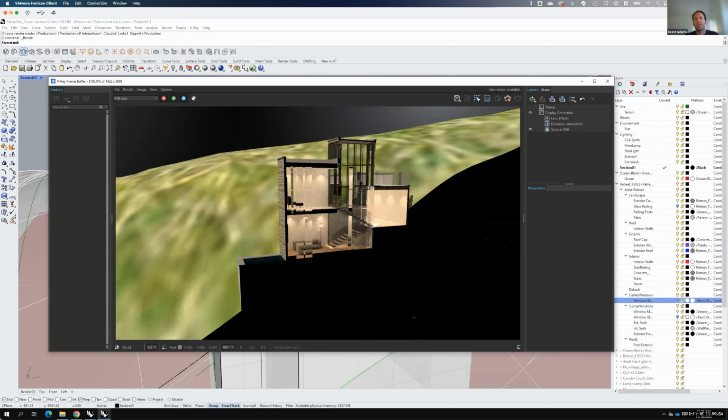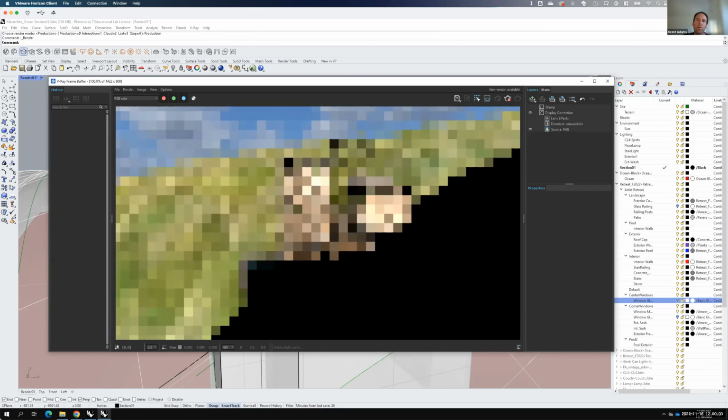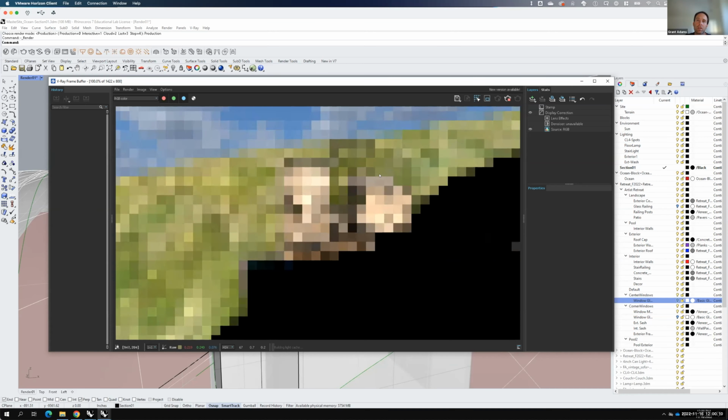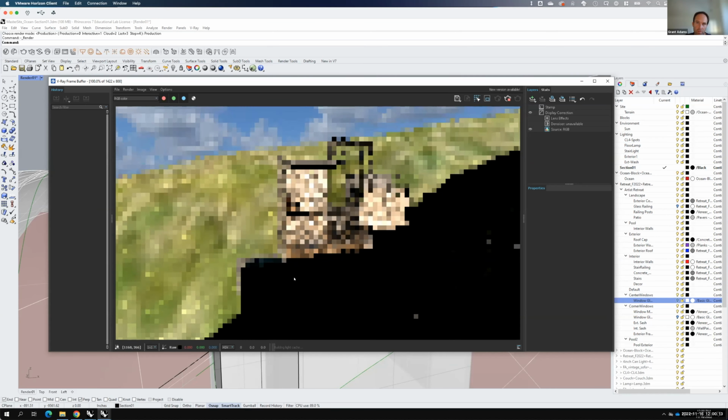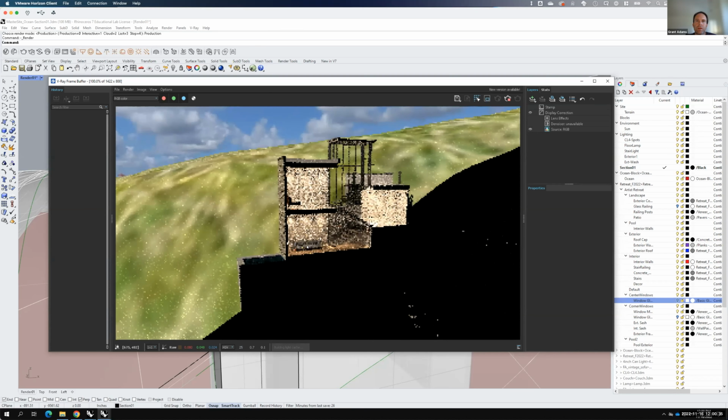So our job today is just to learn to create this section and go through the process of creating the section. That's really what we're after. We will use this section down the road when we create our plan view, when we create our section view and our line drawings. But sometimes people just like to create a section like this so that they can perform a sectional rendering, which is kind of a beautiful rendering in and of itself. So you could set up the view similarly and essentially chop off part of your building and see what it looks like. So as I start to let this render out, you can see that we're seeing inside the building. We filled in all of the building items here that we've cut through. And we're getting a good view of what the inside of this building looks like.